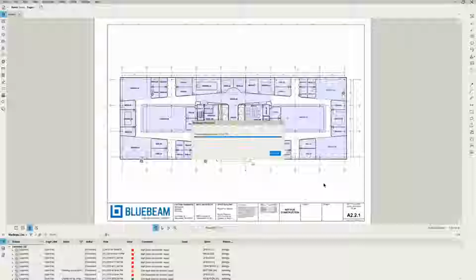Typically, if you do replace pages, there should be an option in there. I can't remember exactly what it says, but to retain the comments. That's one way of doing it. You can also insert comments from another PDF. That's another way that you can get those things to transfer over, copy and paste if something goes wrong. So there are definitely ways of getting these markups and space information to transfer over to the new PDF. So anyhow, I just wanted to mention that as well.